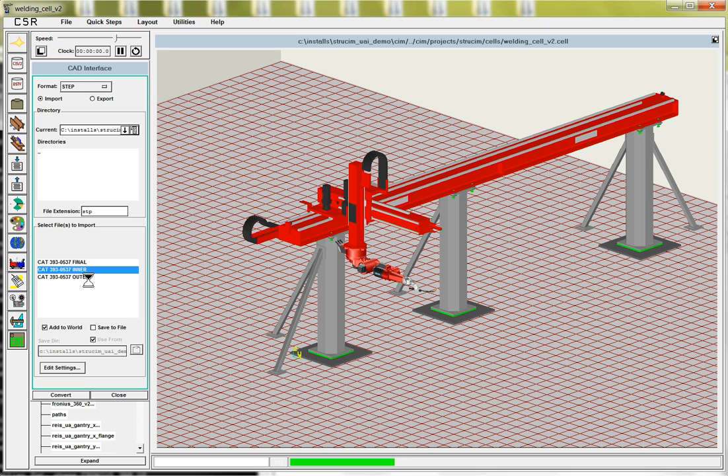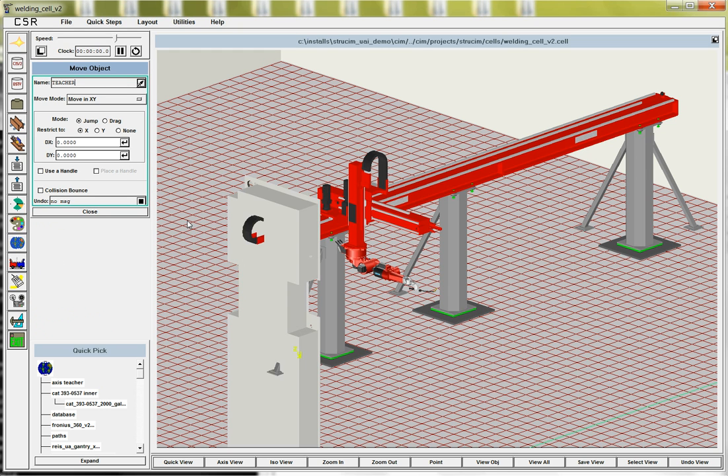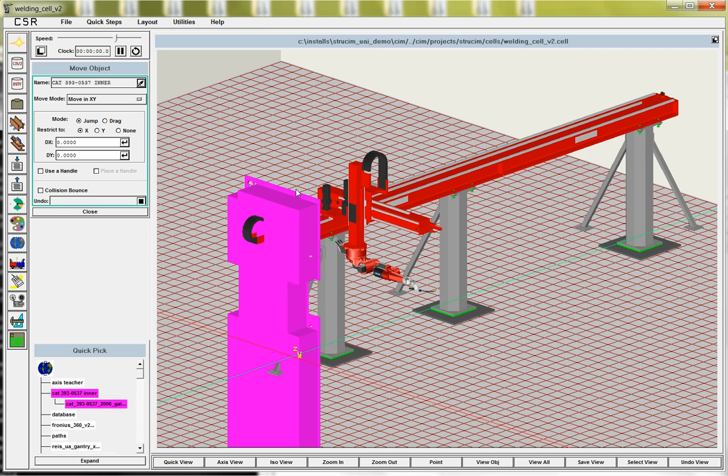2000 series. Our philosophy for welding is to identify subparts, the base and the subparts, and then give subparts certain characteristics so that if we encounter them again, we can weld them. If they're moved a little bit, it doesn't matter. We don't want to just click on surfaces and get welds, because then if there's slight variations, we'll have to do it every time.